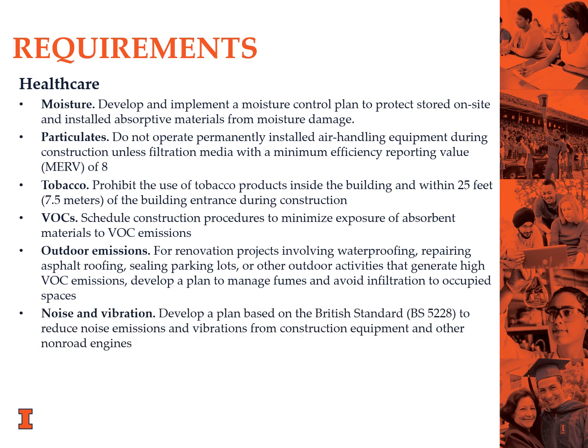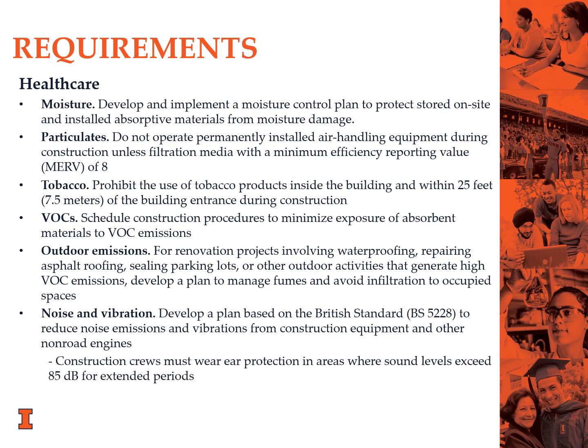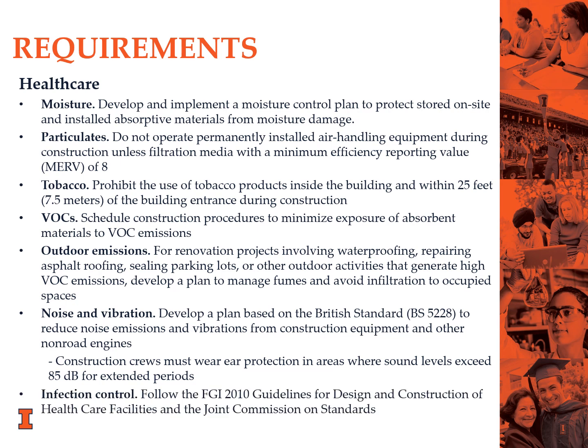For noise and vibration, a plan must be developed to reduce noise emissions and vibrations from construction equipment. Construction crews are required to wear ear protection in areas where sound levels exceed 85 decibels for extended periods. For infection control, the FGI 2010 guidelines for design and construction of healthcare facilities and Joint Commission on Standards must be followed.